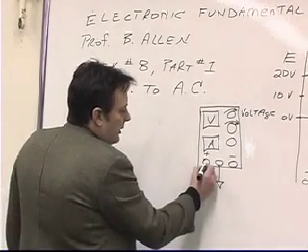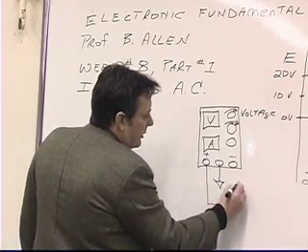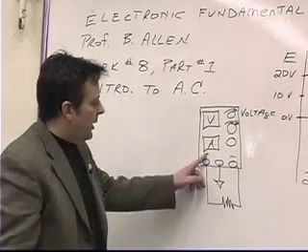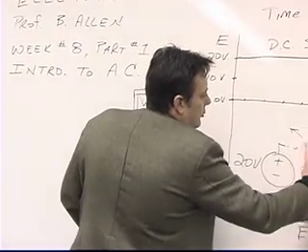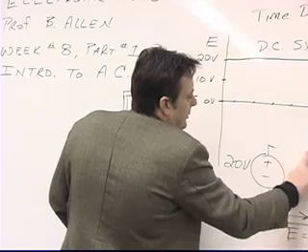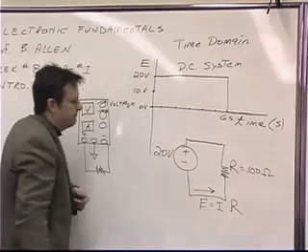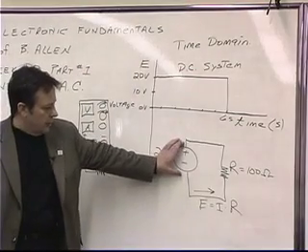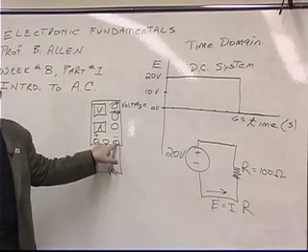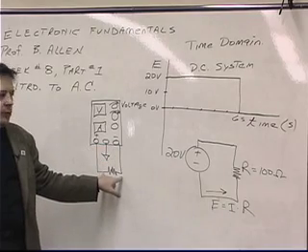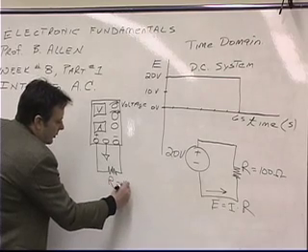And we're going to hook up the resistor that we have in the circuit to the positive and negative terminal. So basically we have this same circuit, but I'm going to redraw the switch as a closed circuit so that current can flow. So basically, here's our voltage source. This is where we're getting our voltage from, our regulated power supply. And this is our load resistor right here. So this is the resistor, which is equal to 100 ohms.